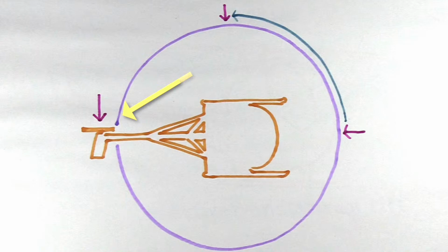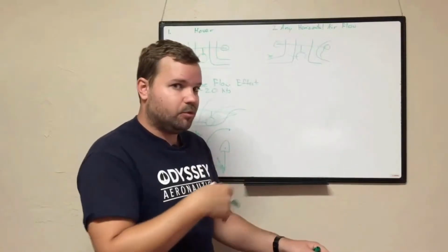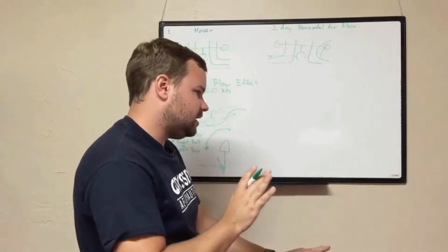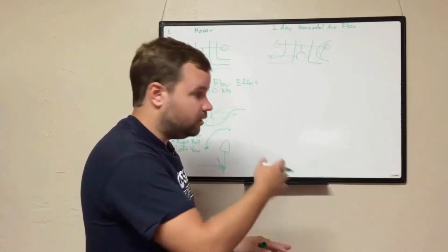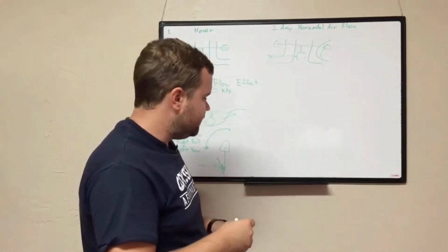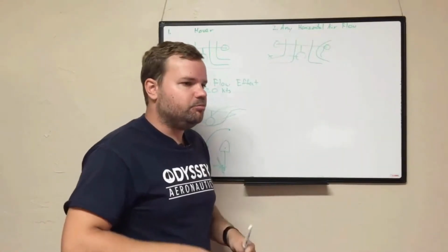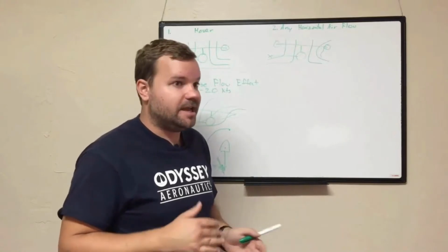So your tail rotor will become more effective, which means it's going to push harder, which means all that left pedal you have in for hover, now that tail rotor is going to become more efficient, so it's going to yaw you to the left. So as you're pushing through this, you need to be backing off that tail rotor and pushing some right pedal to keep your nose straight ahead. Now this is really a funky transition that takes a while for students to get through because they're not anticipating it.